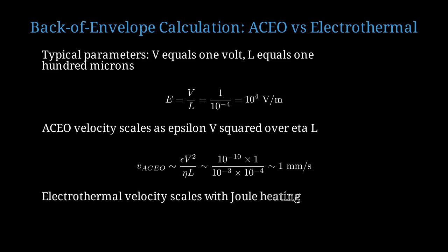Electrothermal velocity depends on Joule heating. The temperature rise scales as sigma E squared times L squared divided by thermal conductivity.